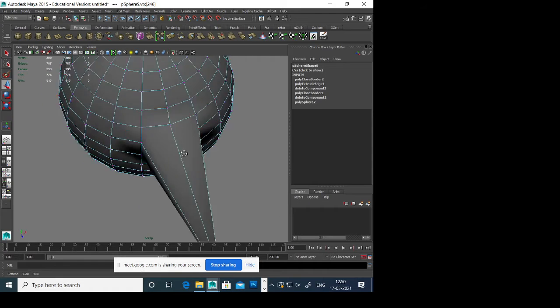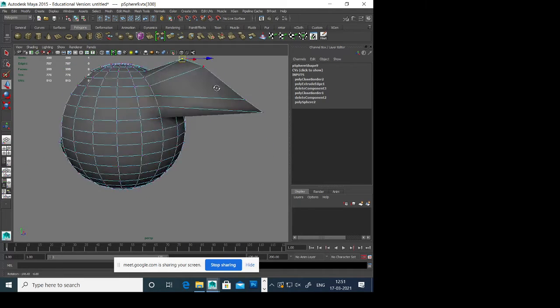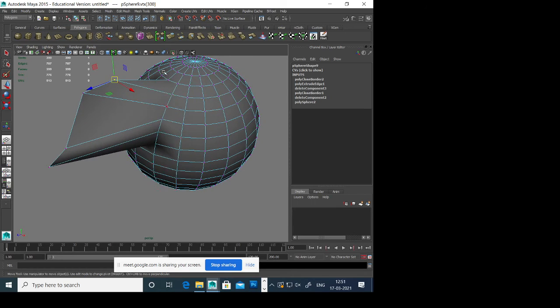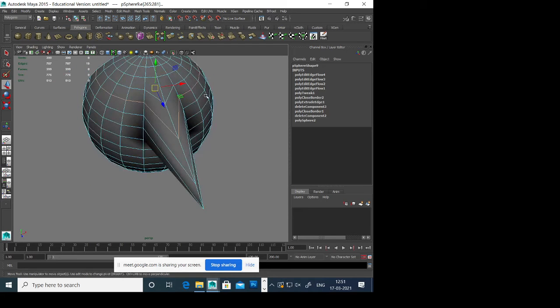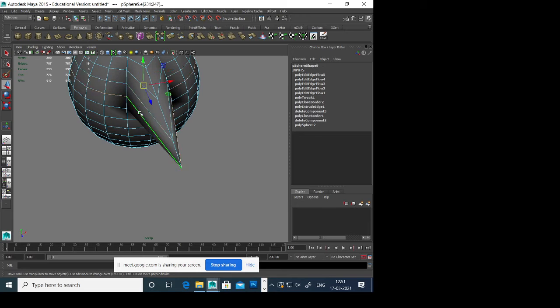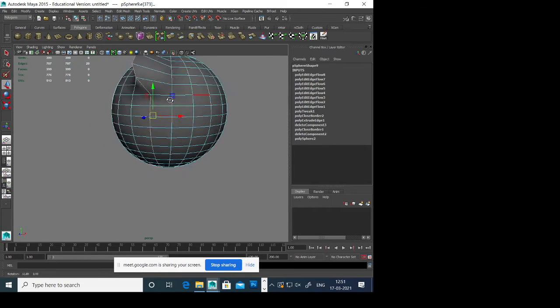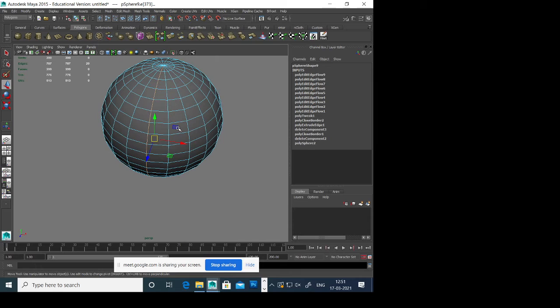So suppose I create something, some spikes, some nonsense geometry. Okay, I created some random something, but I want to evenly distribute my polygons. In that case, I'll double click, select this, shift, right click, edit edge flow, G, repeat. Based on the nearby polygons and vertices, it will average out this thing. You see, it went back to the original shape. Just select this entire loop, G. It averages out the entire thing, so it makes things very easy. Whenever you want to spread your UVs or polygons evenly, it works really fast.